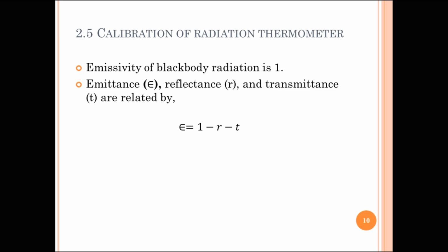It has an automatically controlled system with an accurate sensor such as a platinum resistance thermometer. It can be used from -20 to 3000 degrees Celsius with a maximum emissivity of 0.999 instead of 1 for a blackbody, and the corresponding deviation from the blackbody radiation is expressed in terms of the emittance of the measured body.